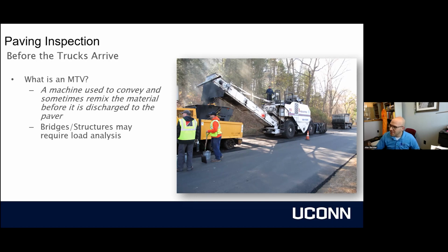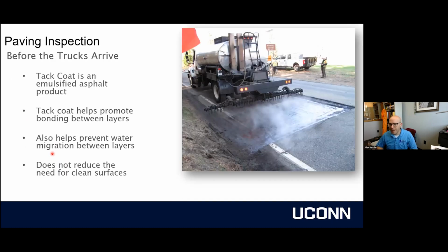The one concern with using material transfer vehicles is because they're so large, you might have exceptions to using them near bridges that are restricted to certain loads. So that's the first thing you want to look at. The next thing you want to make sure you have on site is a tack truck. Tack coat is that thin asphalt and water mixed together. And the idea is we've blended small particles of asphalt in water to make as thin an application as possible.